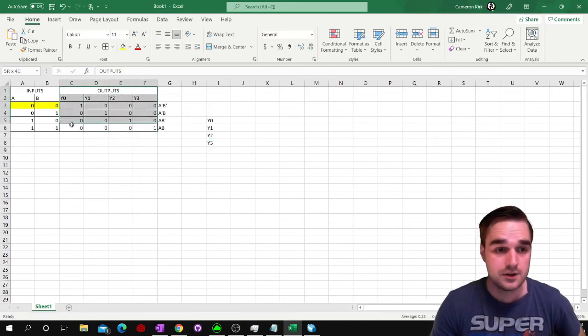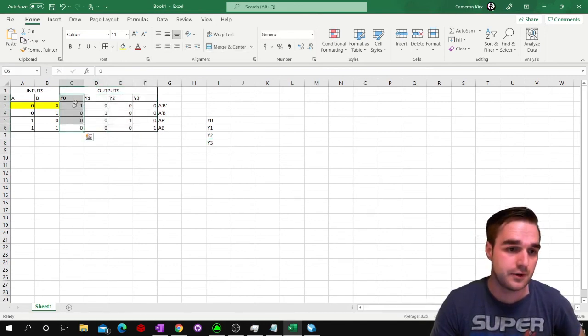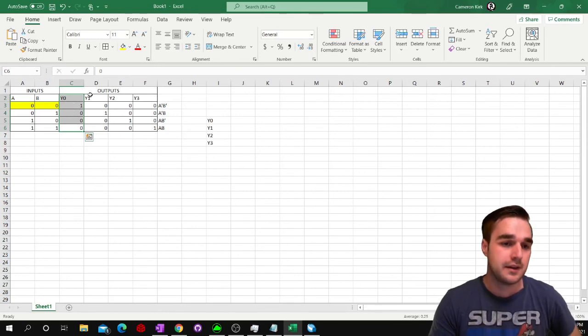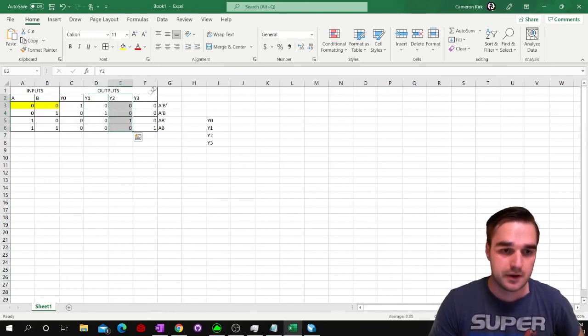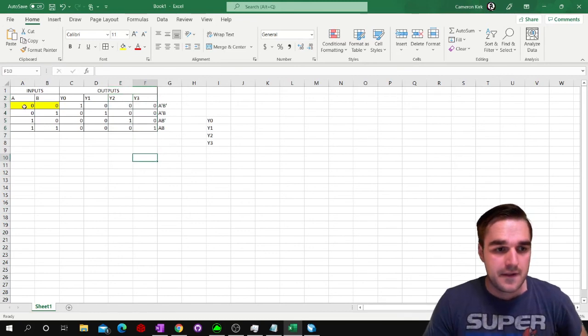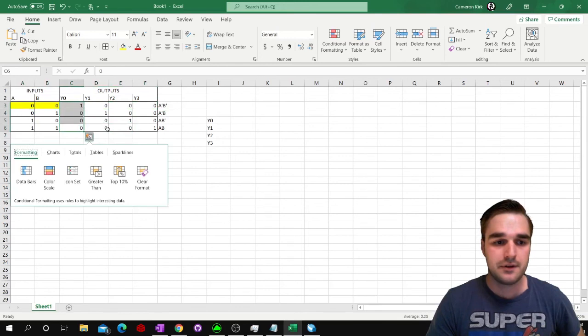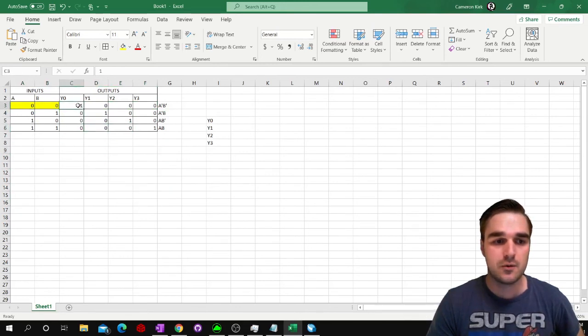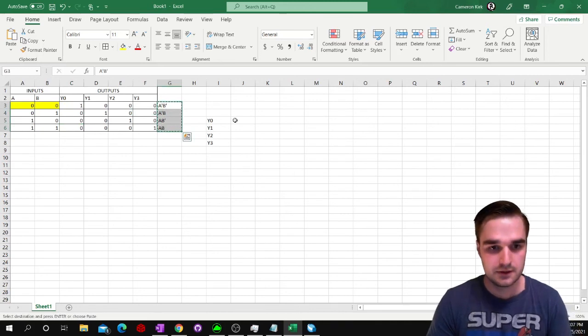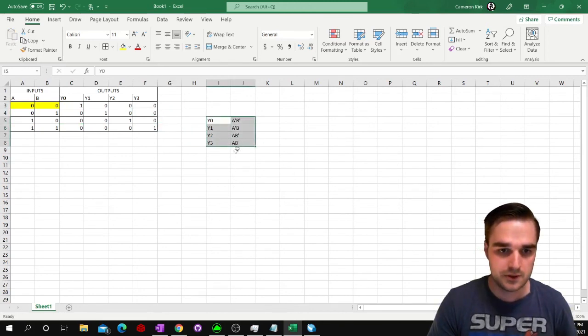You're going to take just this first column and handle the case where you have just this first column. You'll do the k-map, you'll get the equation, and you now have to implement the logic just for that first output, and then you repeat the process for all the outputs. So hopefully that makes sense. But this particular example is simple enough that we don't have to do the k-map. We can just see that y0 is going to be true when we have a naught, b naught, and then it'll be off for all the other cases. So really, these are the equations for each of the outputs.